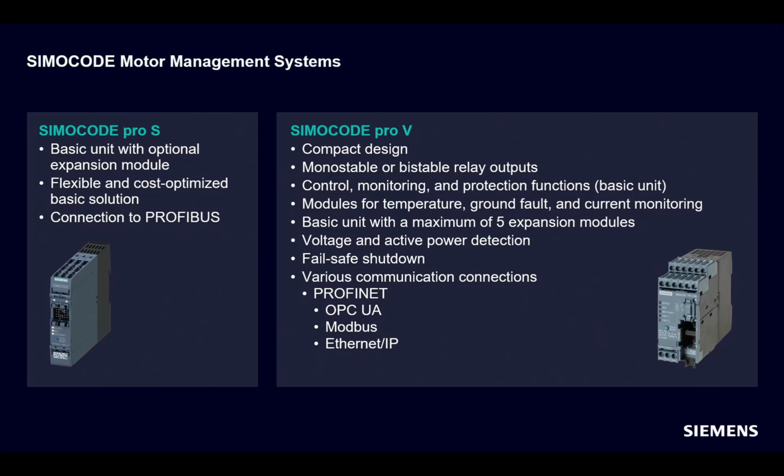The three-phase interruption means we have no longer transport of energy. The other side is maybe without voltage, but it's not a critical thing, as nothing explodes. But if you have a ground fault, for instance, in a big motor in a chemical plant, you have a single-phase interruption, and a motor or a generator doesn't like that.